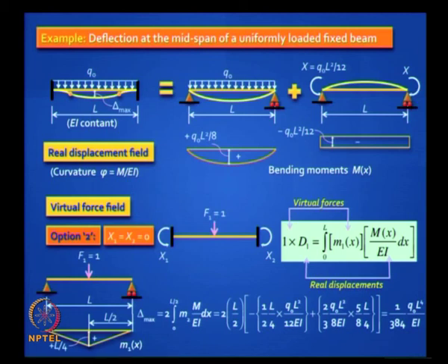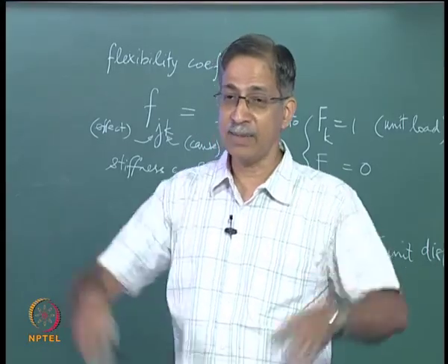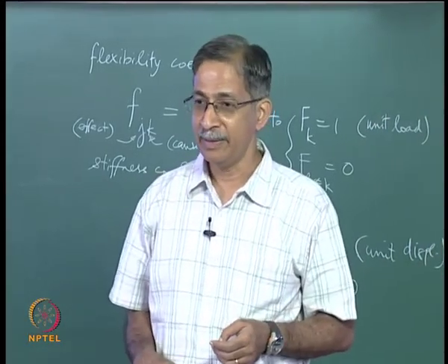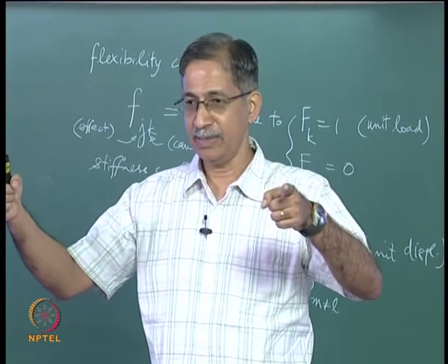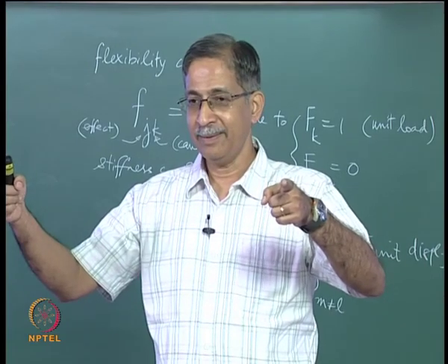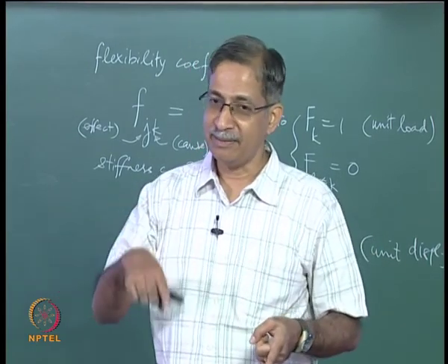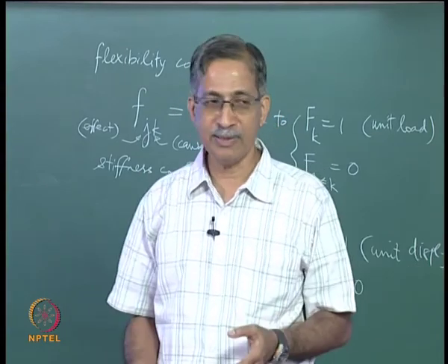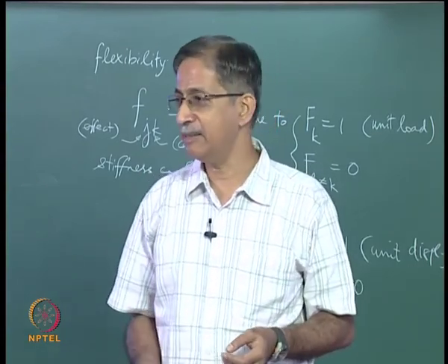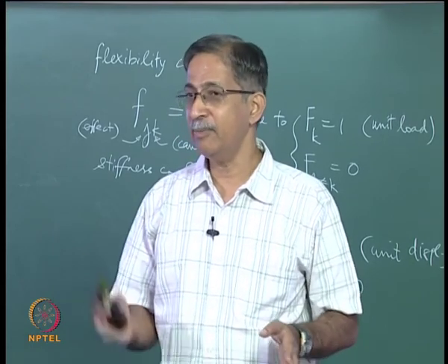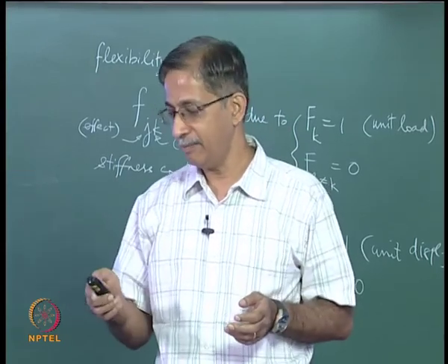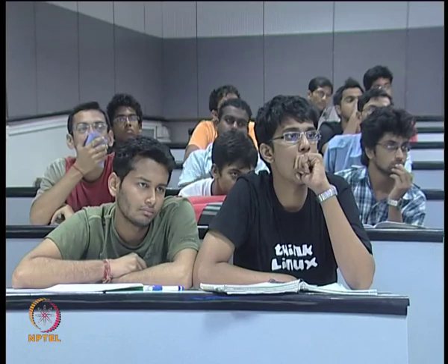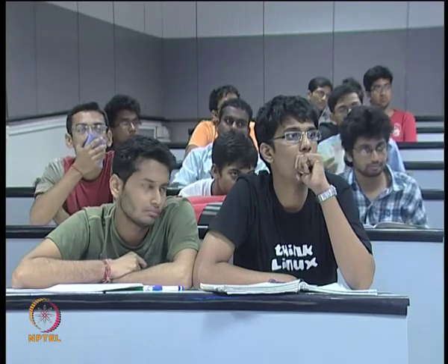It shows the real power of the principle of virtual work, which means what are the implications of this? You take a complicated structure, a multi-storied frame, if you have the bending moment diagram in any one beam, that's enough for you to get the deflection in that beam, because you can strip it off from the rest of the structure and make it statically determinate, apply the unit load method. Similarly, we will see this later, you can find the drift in a tall building very quickly by invoking this method. So we will stop here, we will continue in the next class.